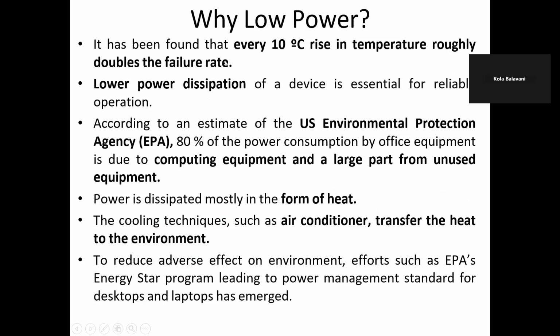And we know it has been found that for every 10 degrees rise in temperature, the failure rate roughly doubles. That's why low power dissipation of a device is essential for reliable operation. And the power is dissipated mostly in the form of heat only.